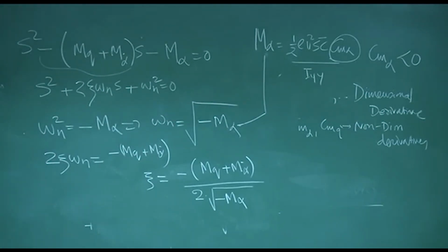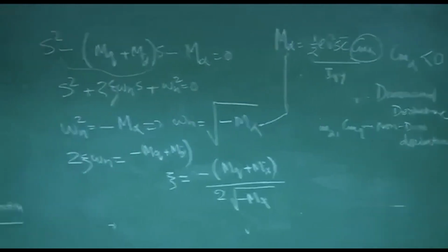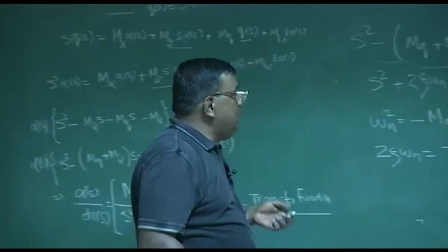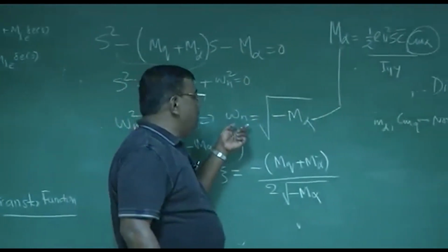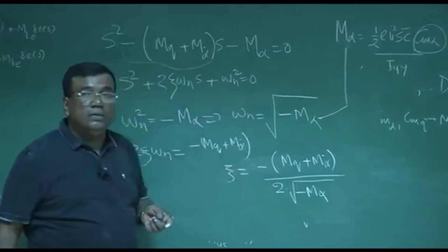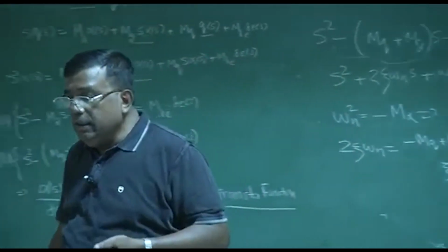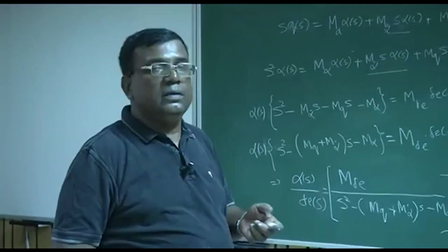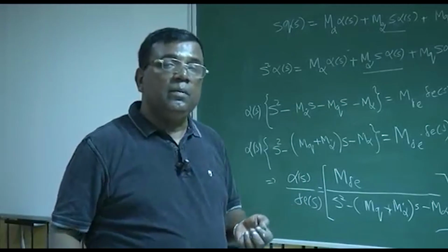Okay? This is a very simple way of handling a pure pitch motion through modeling, and we'll check when you'll be solving the sixth equation of motion, and you'll be getting a solution for some motion closer to pure pitch, how much they come close. And that way you can take a decision, especially in the design stage. You don't want to solve those big equations because you don't have complete information.